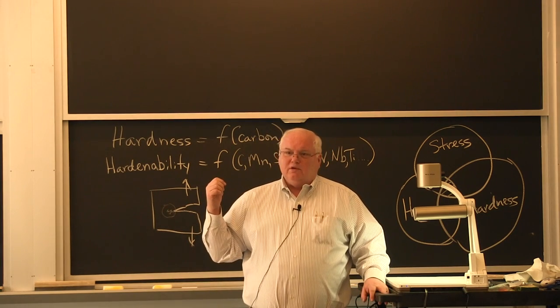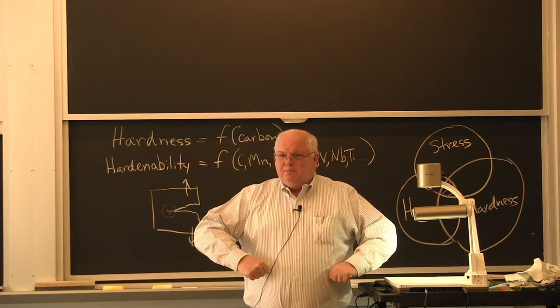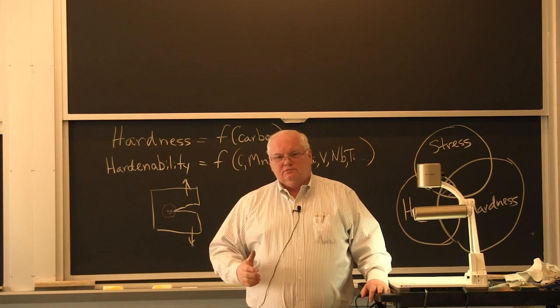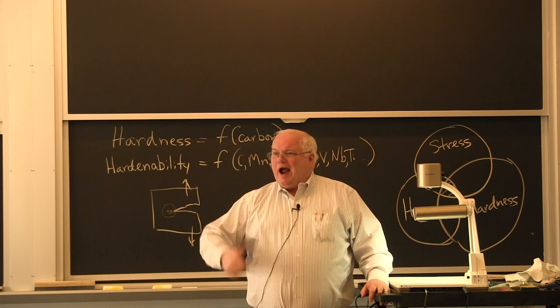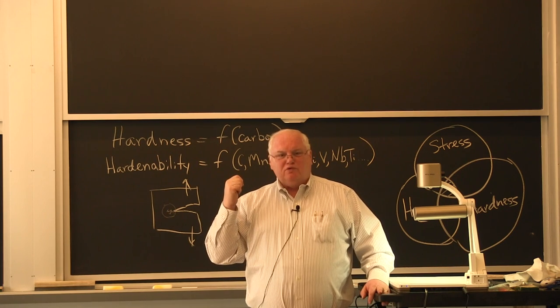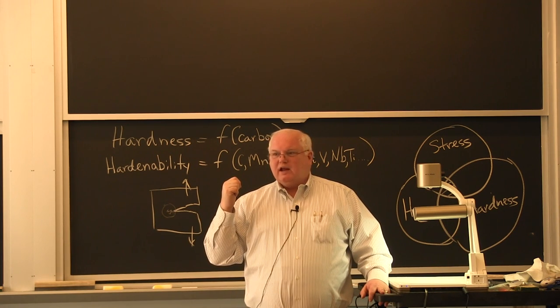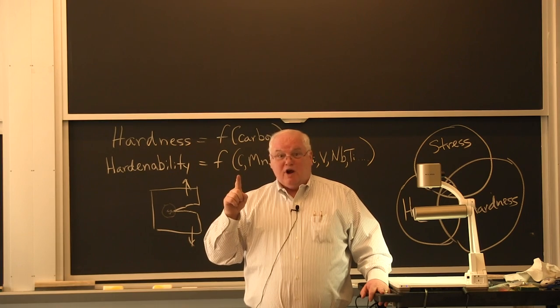and so some guy welding at night would hear this piece that had been welded during the day, and it'd be a big boom like a rifle shot. A hydrogen crack just ran through the part they had made that day, 8 hours earlier. Delayed cracking.